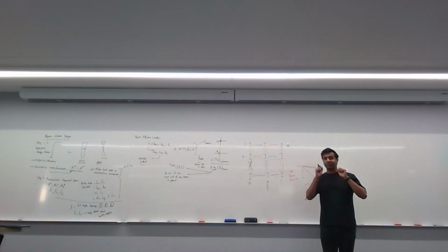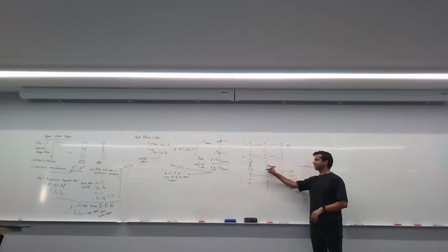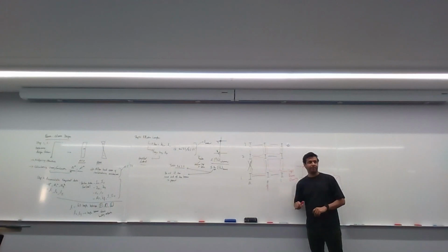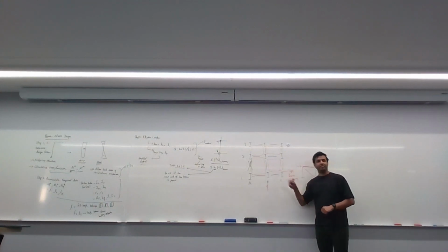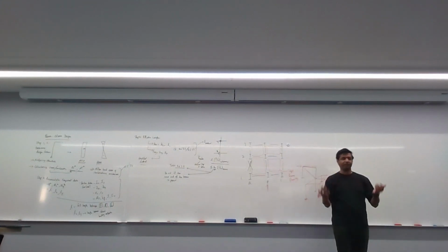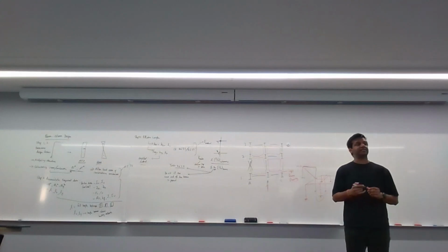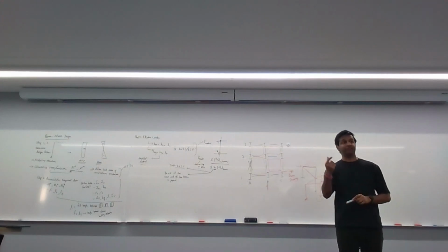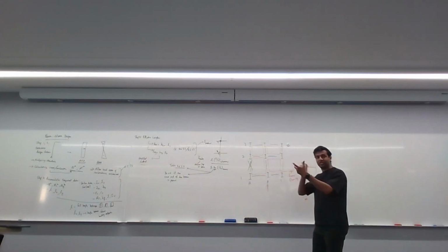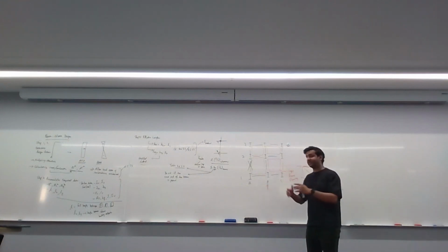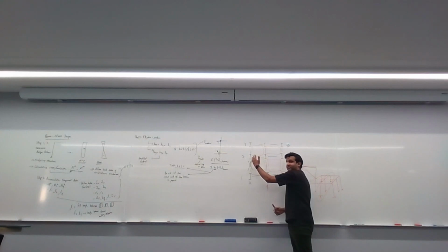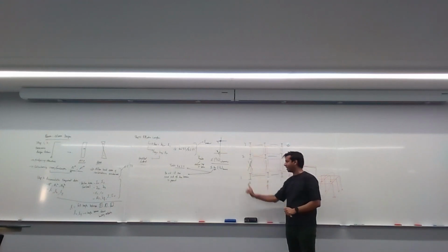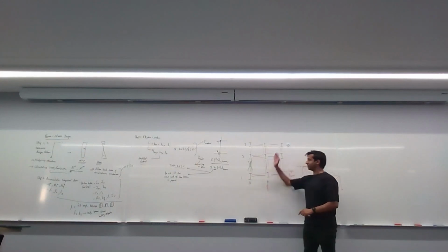Now, the question you've got to ask yourself is, what is connecting this and this? I've said it's light frame flooring, or lightweight flooring, however you want to call it. It means that it's a flooring that isn't stiff. It's squishy, it can bend. So if this frame is braced, it means this frame isn't going to move. This frame is going to stay still no matter how much force you apply here. What about this frame? Move independently.